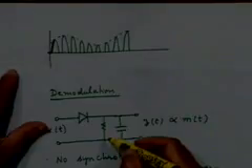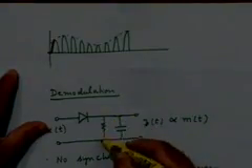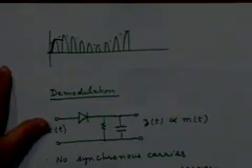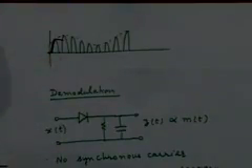However, due to the fact that there is a resistance here, there is a discharge phenomenon that will take place. So this voltage value starts to decrease a little bit depending on the time constant of the discharging, right? So let us say it discharges slowly, and this is the way it will discharge.